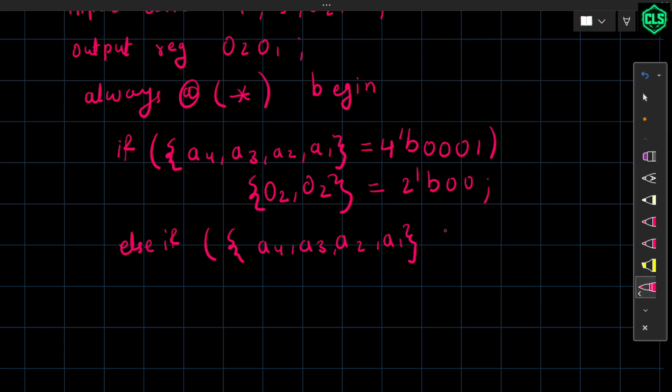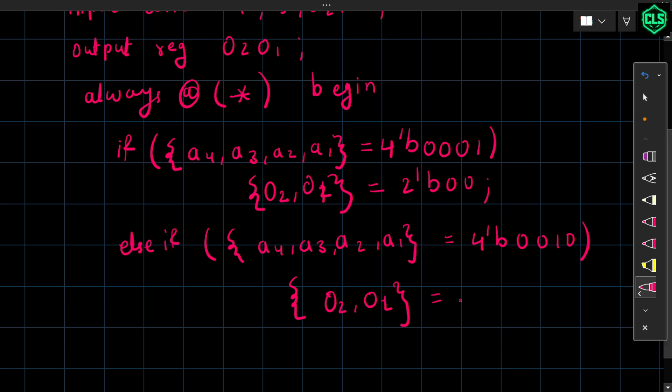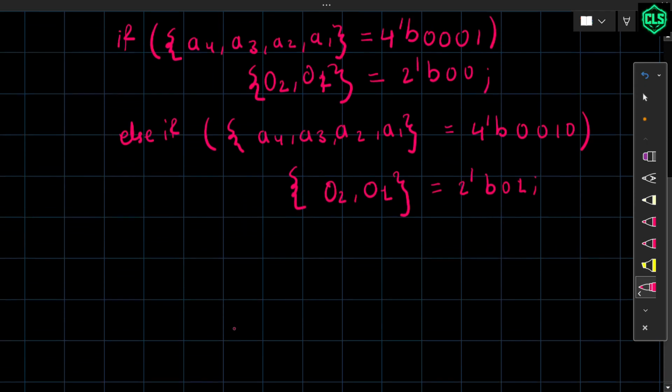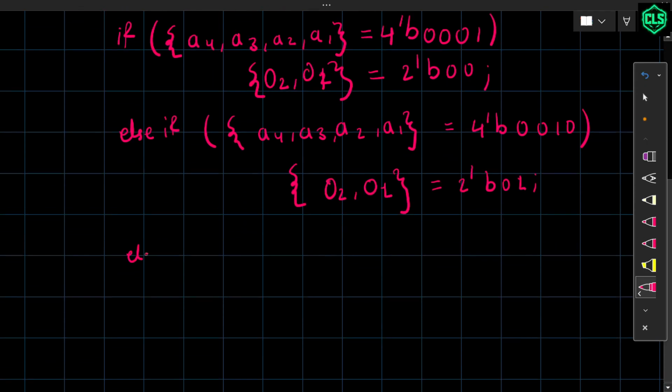For that, 4'b0010, if there is, then our output here is 1, and here will be 2'b01. Okay, let's continue writing else if.